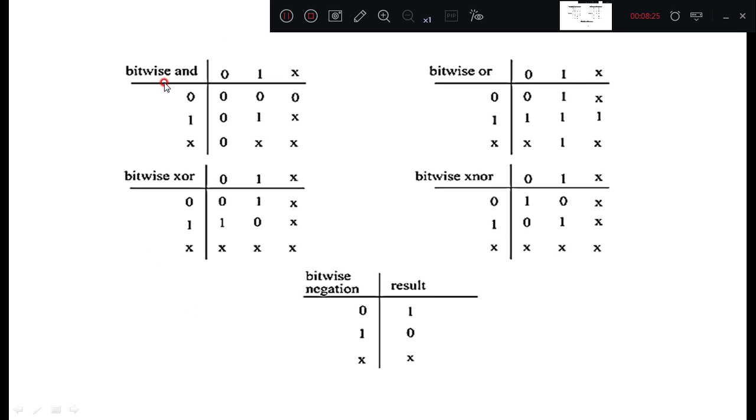If you see, generally it has 4 values 0, 1, x, z. Since z is treated as unknown, we write 0, 1, x. For the AND gate, for 0, 0 you will get 0; 0, 1 you will get 0; 1, 0 you will get 0; for 1, 1 you will get 1. For the remaining combinations, 0, x you will get 0; x, 0 you will get 0; 1, x the result is unknown; x, 1 also unknown. When both inputs are unknown, the result is unknown.